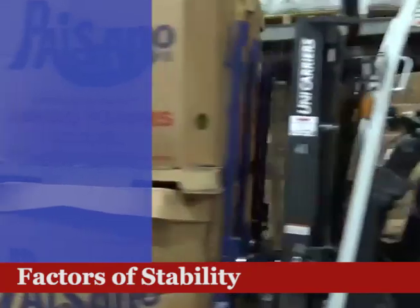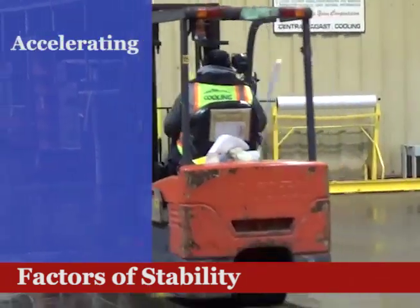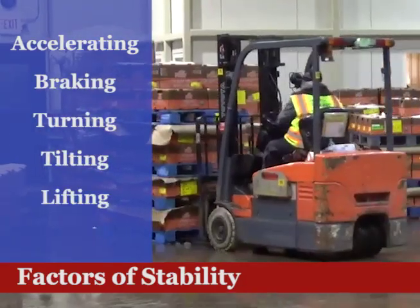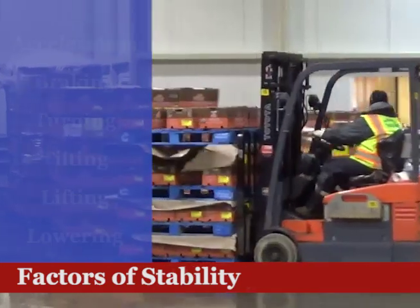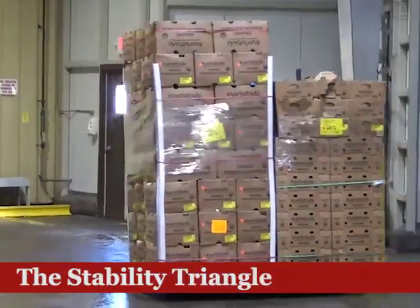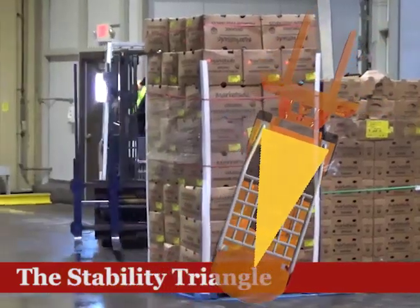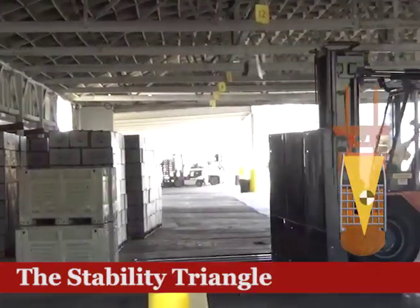There are many other factors that affect the combined center of gravity. Accelerating, braking, turning, tilting loads, lifting loads, and lowering loads, all move the combined center of gravity around the stability triangle. Let's take a look at a few examples of forklifts in operation, and watch how the center of gravity shifts while the driver performs normal material handling tasks.